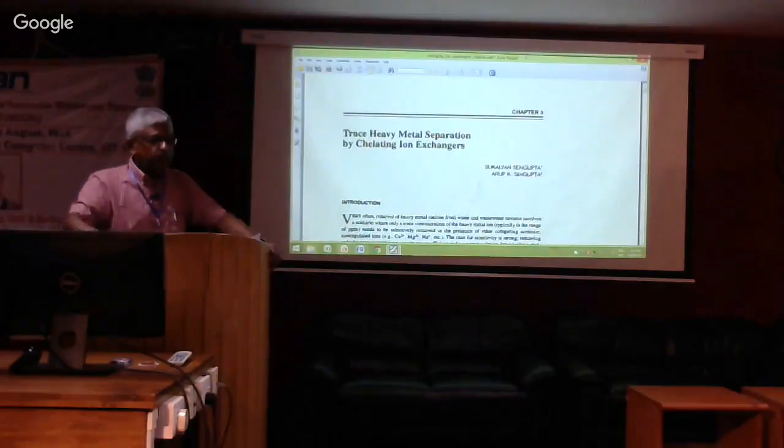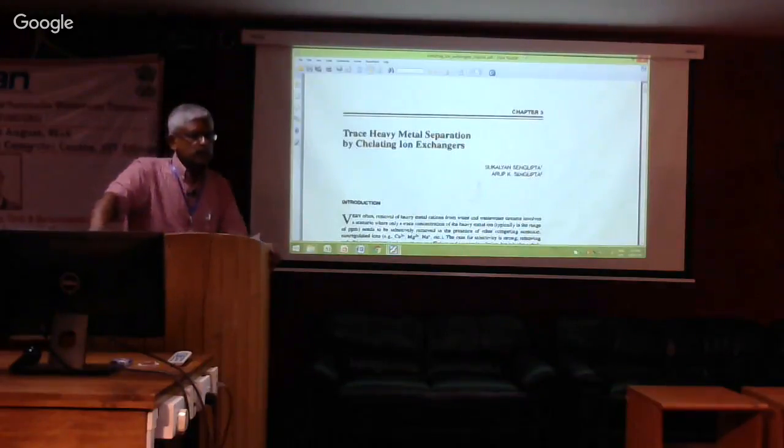Now, I think the latest data that my student sent me over email is about 10 milligrams of ammonium nitrogen per gram. That is the capacity. And the regeneration, I think we are about 88 to 90%. But as I said, there is this tail which is a bit of a challenge.